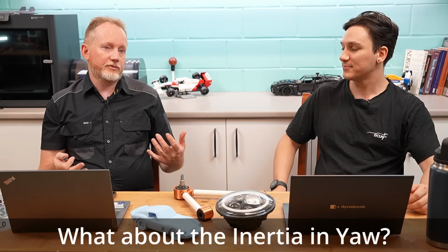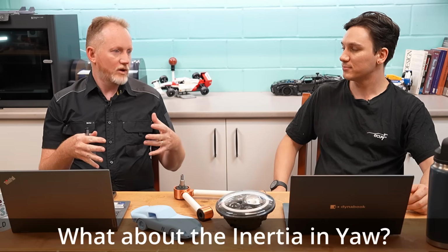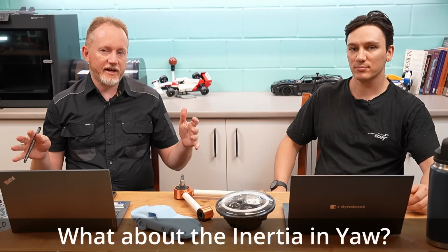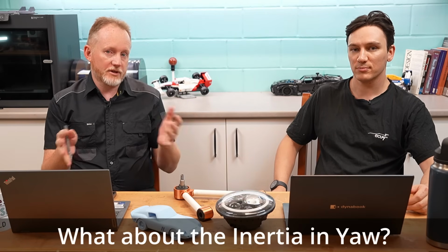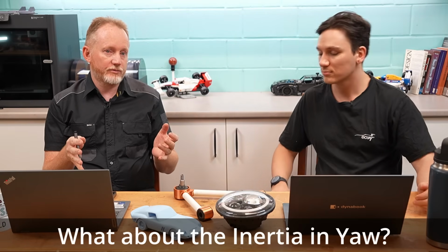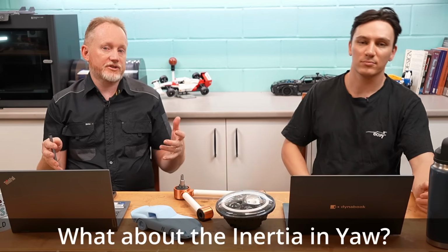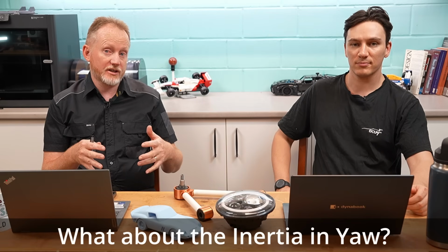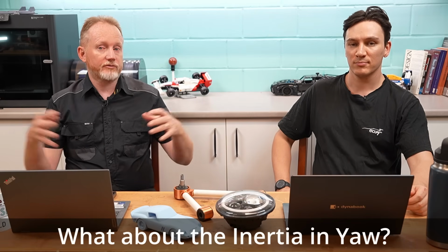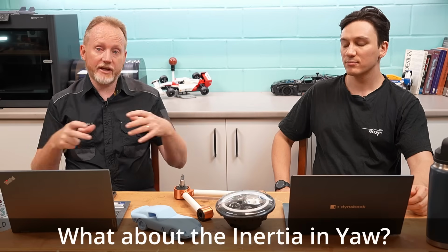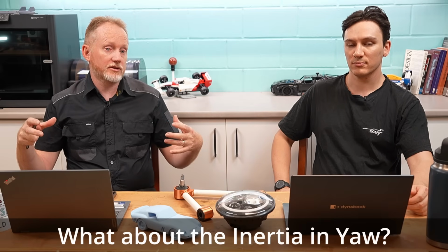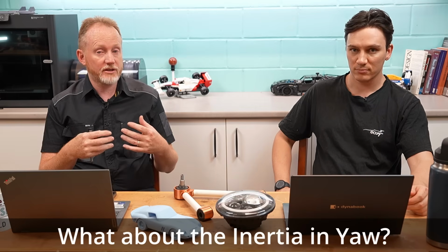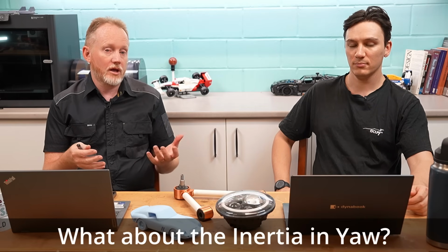I think there's only really one decision. When you're building these small two-seater cars, there's not really any luggage space or anything like that. You're already a small, light car. You're already going to turn pretty rapidly. The only real decision you've got is, are you going to make that a front-engine car or a mid-engine car? If it's a front-engine car, you've moved the masses of the driver and the engine further apart from each other, so your moment of inertia in yaw is going to go up. So it's going to be slightly more stable.